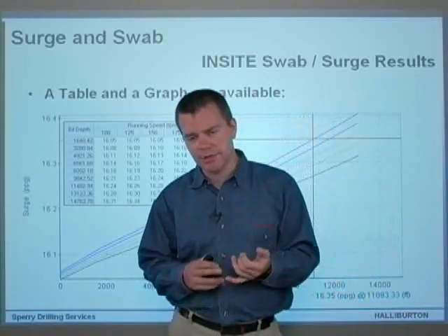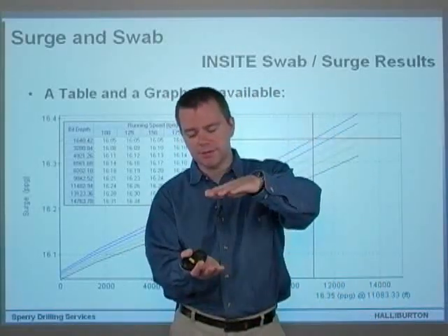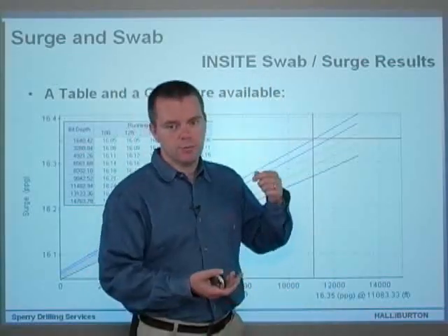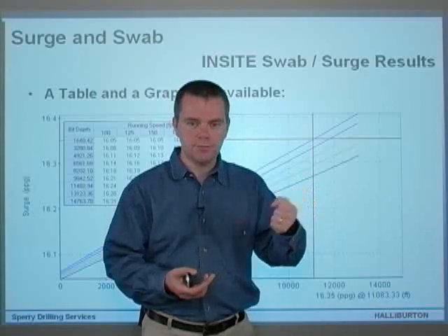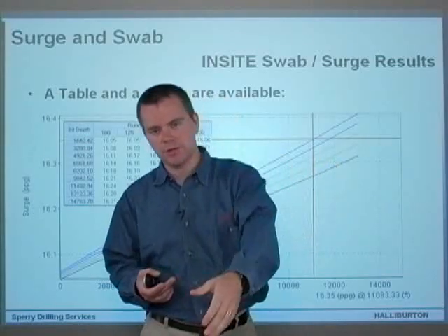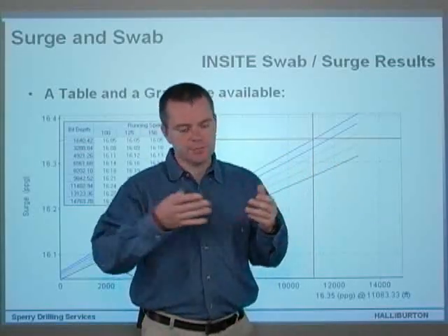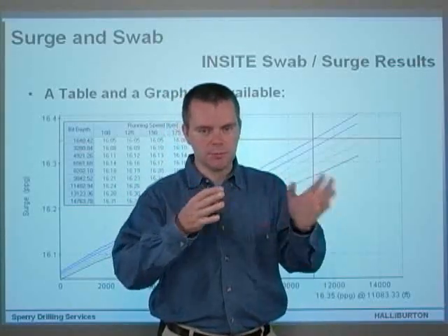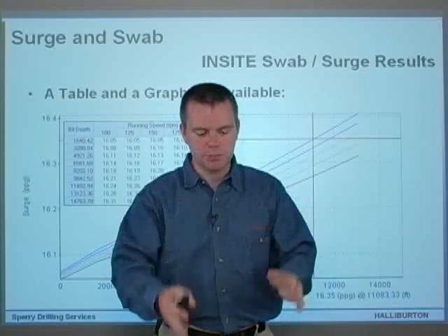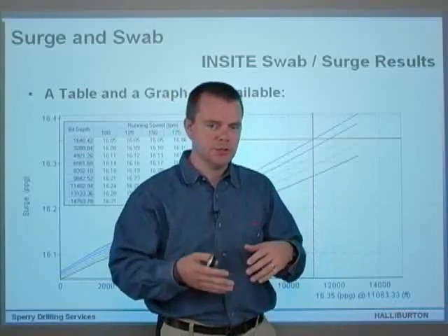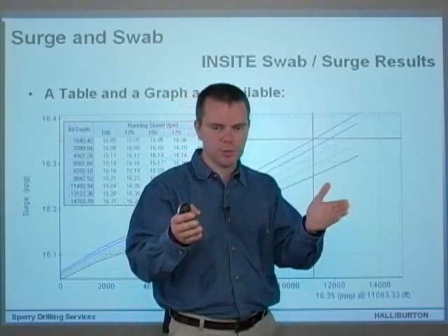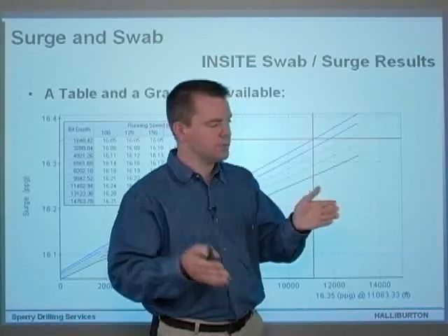So instead of using fracture gradient and pore pressure as my limiting factors, what I tend to do is look back at the PWD data when we're drilling, as we're picking up before a connection and running down after a connection, maybe looking at whether there are gel spikes on the PWD, just seeing what the maximum and minimum pressures were that we managed to withstand while drilling, and use the maximum pressure while drilling and the minimum swab pressure while drilling as my limits for tripping.